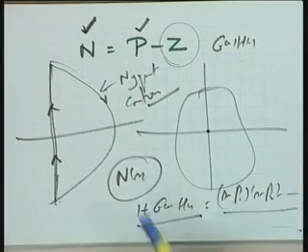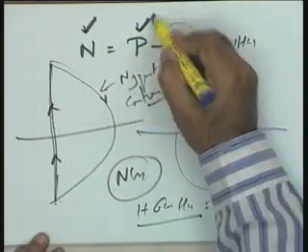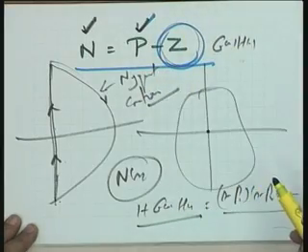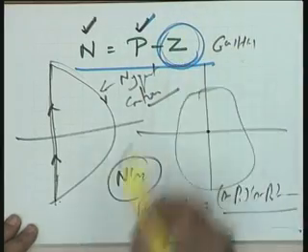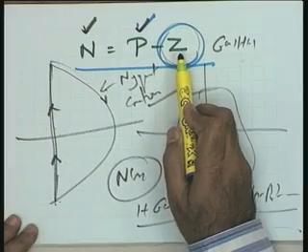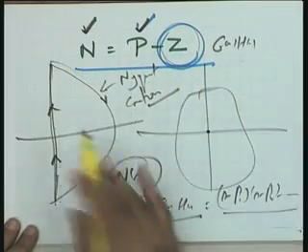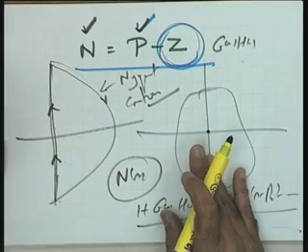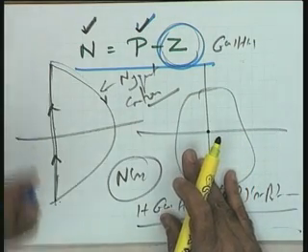It says that n is equal to p minus z. You count n from here. You count p is already known to you. Therefore, from this equation you have z. So in this particular case, you find that these many zeros of 1 plus GSHS are in the right half plane, and hence not only instability but some additional information about instability is also given, as was given by Routh stability criterion. You recall, it gave you the number of poles in the right half plane. This information is available in the Nyquist stability criterion also.